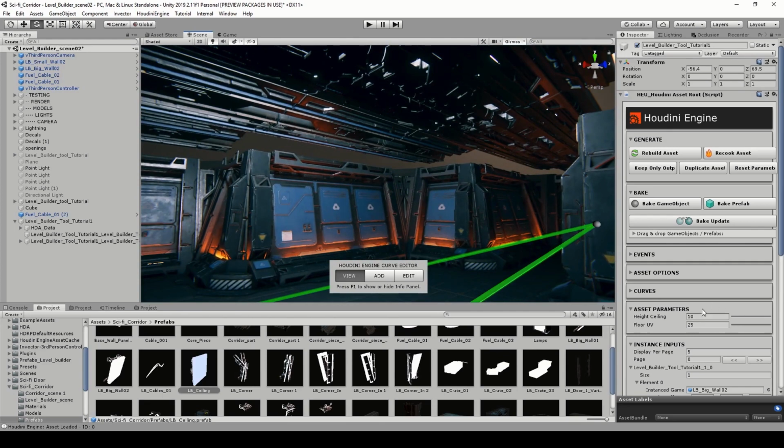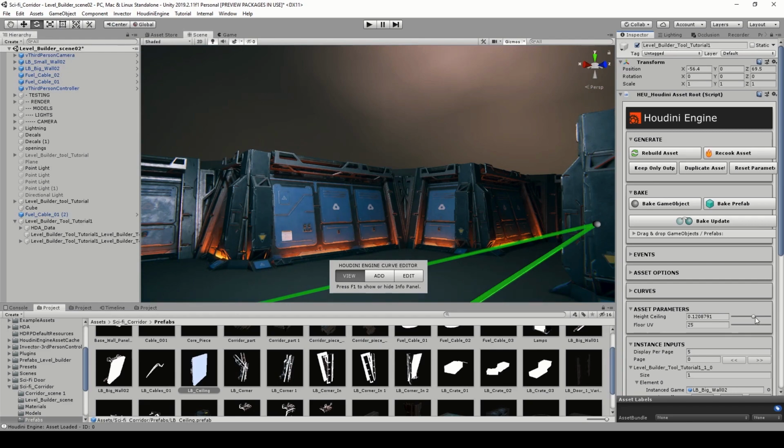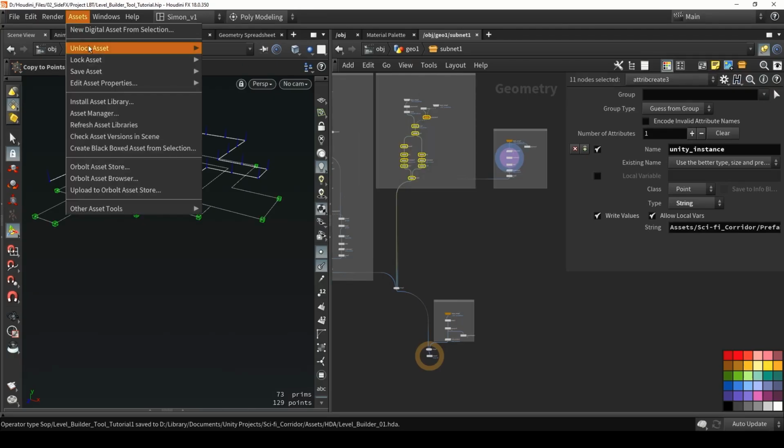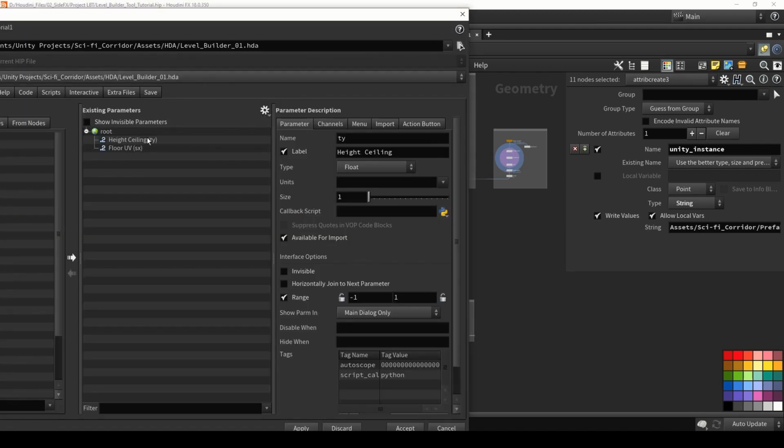And I can also see here I have my sliders. One thing I didn't adjust is the range. So they are not properly set up. So normally you should see like this point, but I didn't set a nice range. So I need to go back, open this menu again. Let's put a decent range. So from, let's say, 2 to 12, and the floor scale should be from 1 to, let's say, 30. And apply,